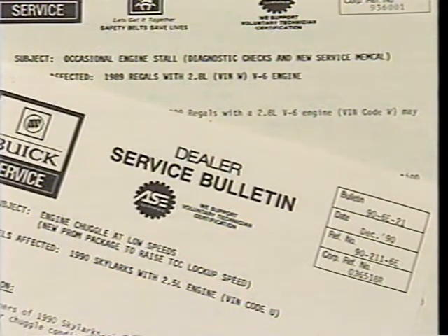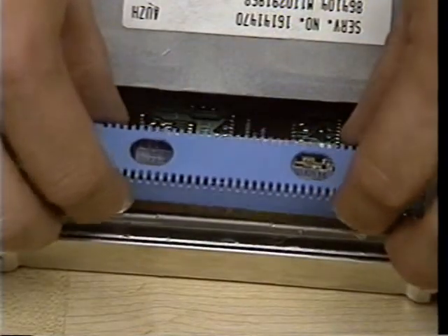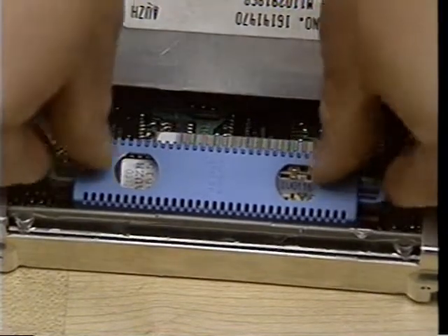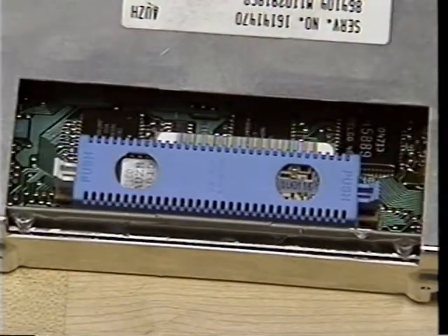It should be remembered, however, that a PROM or MEM CAL should not be updated just because a new one is available. Unless the vehicle is suffering from a specific drivability complaint and a PROM is listed in a service bulletin to correct that specific complaint, the PROM should not be replaced. Otherwise, replacing the PROM does not correct the problem. Repair dollars are wasted, and the customer's car is likely not to be fixed.